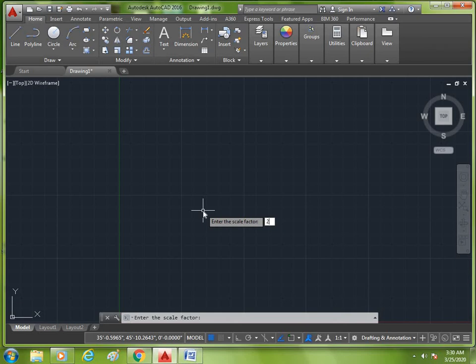But if you want to reduce or shrink the size of your drawing, you can press 0.5 enter. Right now I'm entering 1 because, for simplicity, I want to work on full scale, so 1 enter. Here, 100 feet is very important. If you choose engineering or architectural, this single quote is used for feet, and for inches you have to press this with shift, then you can enter this double quote, that is for inches. So I press 100 feet enter, and 100 feet enter is the paper height.